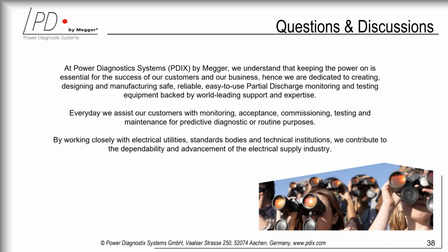Yeah, hello everyone. Good question. Alarm levels, warning levels, that's always the question when we commission such a system. We know from the factory acceptance test a typical acceptance level for an oil-filled power transformer in a range of 100 to 200, 300 picocoulomb, and we try to achieve this sensitivity in the field.